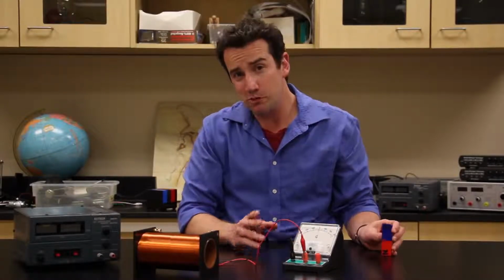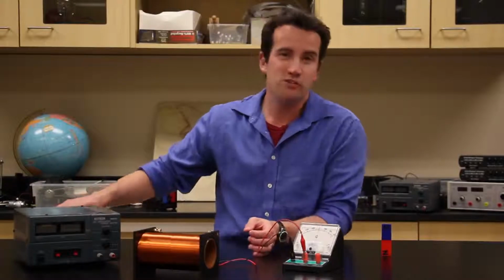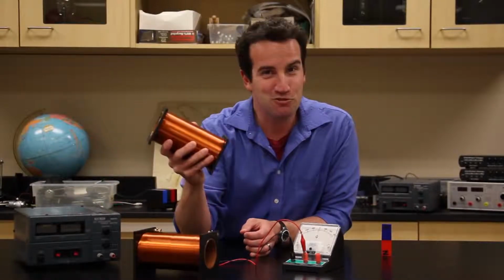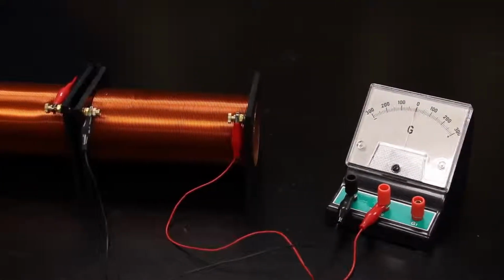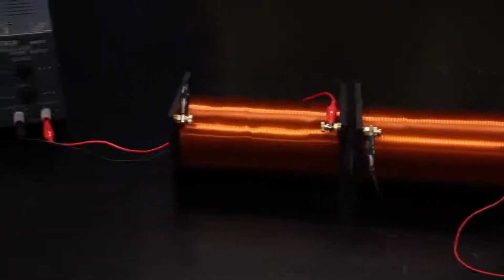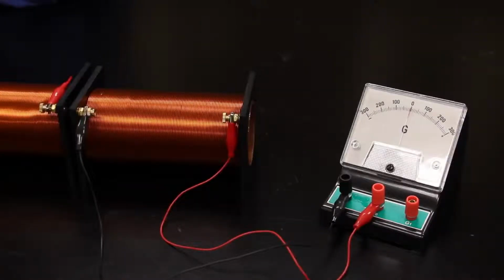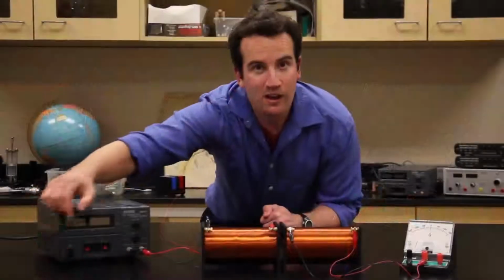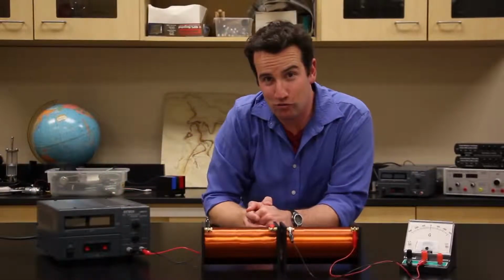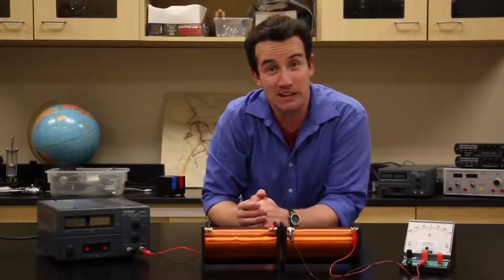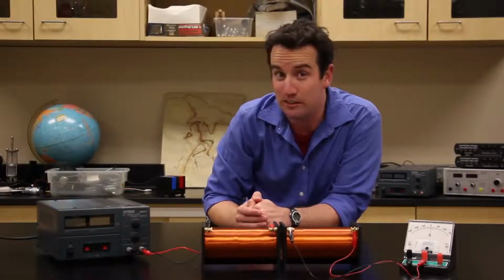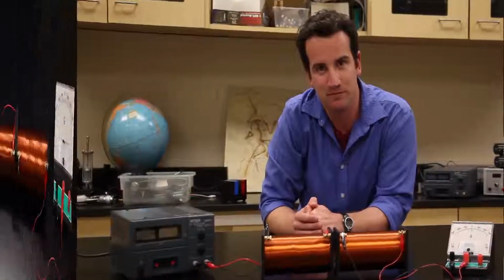Now, the transformer puts both of these ideas together, but instead of using a bar magnet, it uses an electromagnet. When I turn on the power supply, it briefly produces a changing magnetic field in the first coil, and that produces a brief electric current in the second coil. Also, when I turn the power supply off, again there is a brief current, but in the other direction. This is the fundamental design of a transformer. Two coils that are connected magnetically but electrically separated constitute a transformer.